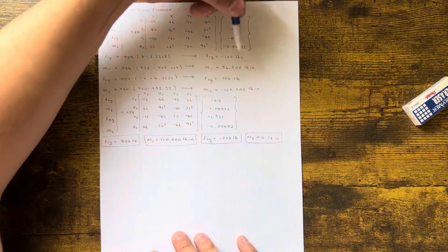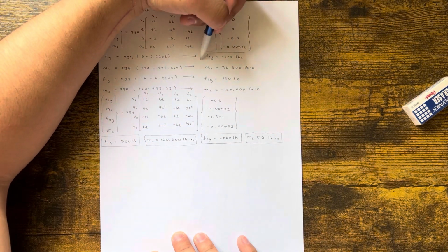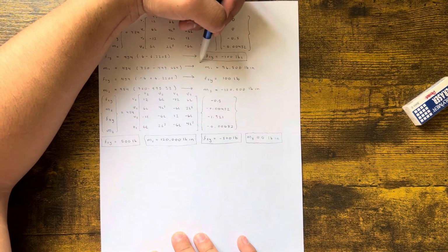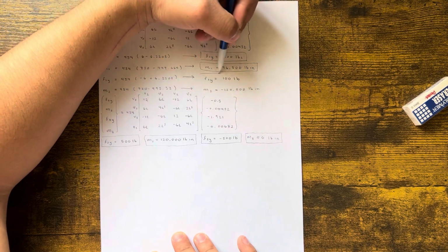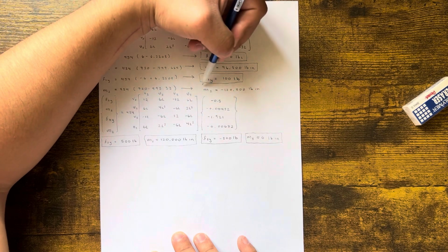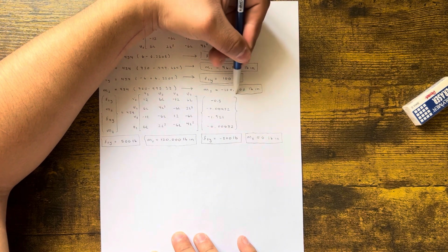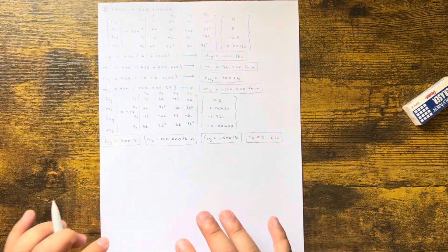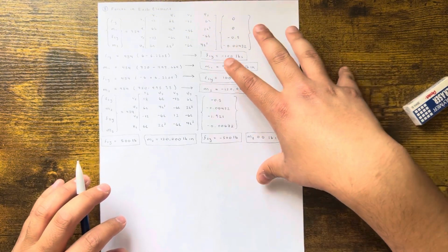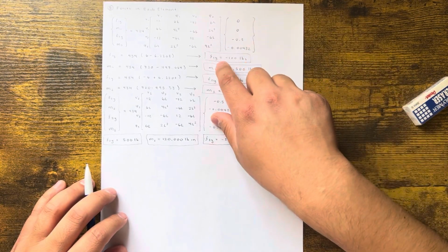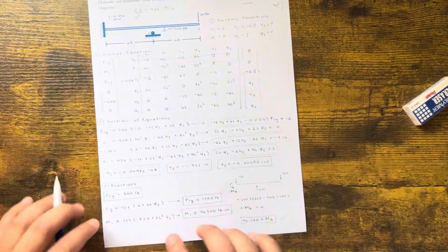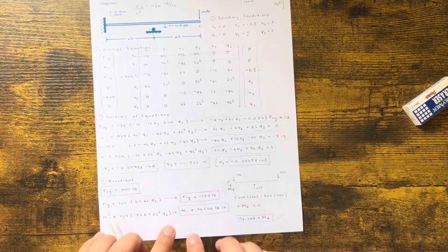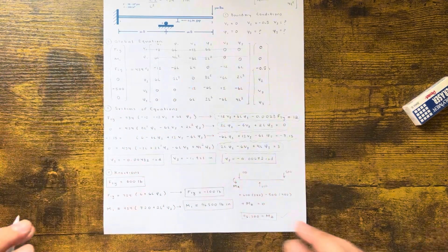In this case, you already found all your force elements, right? This is the second element. We're done. Oh no, I just want to box them up, right? And then check this out. This is how you verify these. When you add all of the same, in this case, all of the F1Ys, all of the M1s, all of the F2Ys, whatever, you should get your big F2Y, your big F1Y, your big M1, your big M2, all that good stuff. So let me show you what I mean.